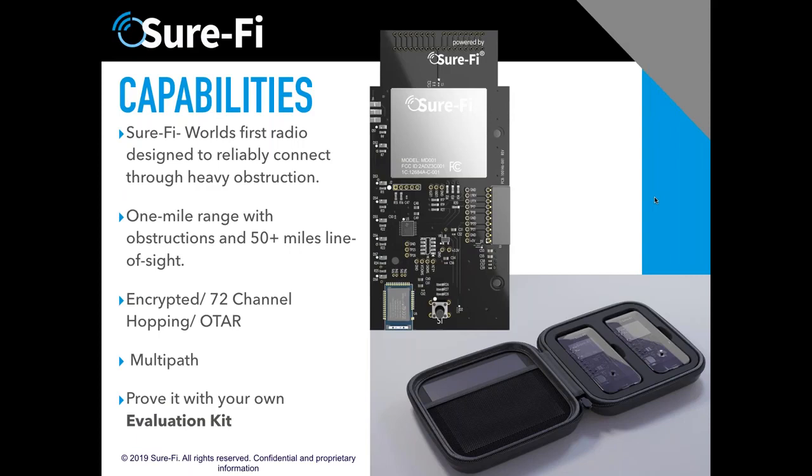Now, I say relatively because yes, we can send Wiegand protocols, we can send RS-485 and 232, which is more, but we've also been working on, and are in development with, the serial data bridge to actually send voice. So within a few months, we should have a unit available that will allow you to do a telephone entry system where you can push the button, half duplex, say, hey, I'm here, will you open the gate or whatever.